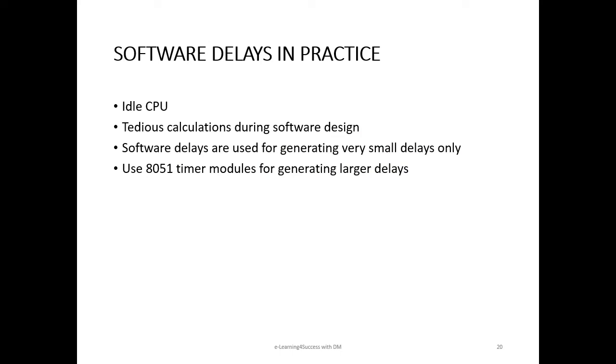Now let us think about the practicality of software delays. We have already discussed that while executing a software delay subroutine, the CPU is not doing any useful task. A software design that takes care of this will be very much complex. Hence, software delays are used for generating very small time delays, of the order of a few microseconds in the case of the 8051 microcontroller. To do this, a few NOP instructions are added between tasks. For generating larger delays, the 8051 timer modules are used. Discussions on this will be done in the next lecture.